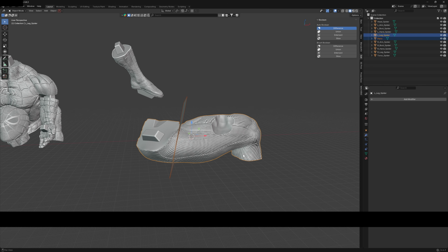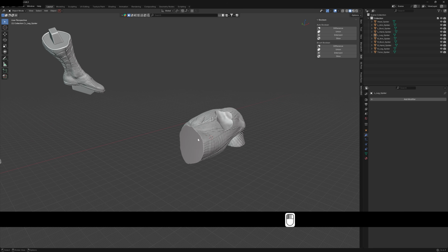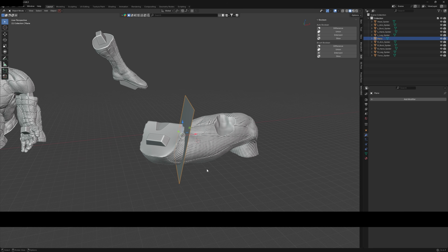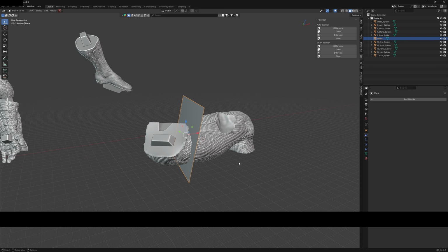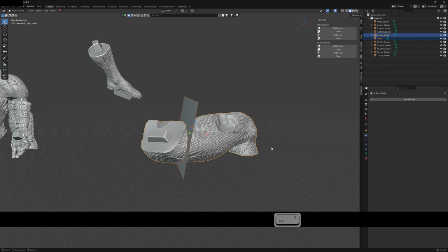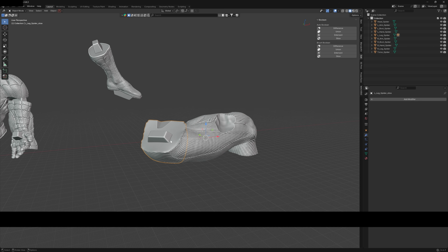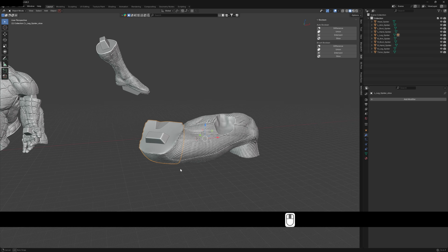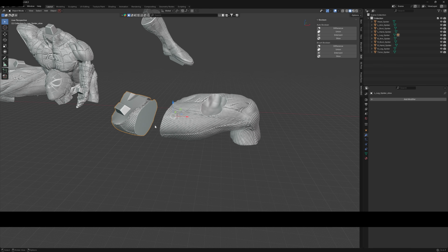If you try difference, it just cuts away just one part and doesn't leave the other part. So with the plane, what we can do is select the plane. That is the thing that's going to do the cutting. That is the knife, and then the object you want to cut, and you can go slice. With Blender as well, if it's not doing anything, you click and it's doing this blue thing and you think it's hanging, leave it. So often it comes back and doesn't crash and just works itself out. So you get 2 separate pieces, but alignment might be an issue.